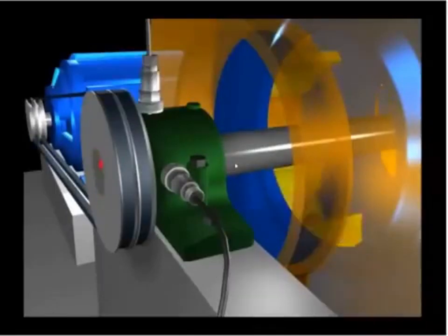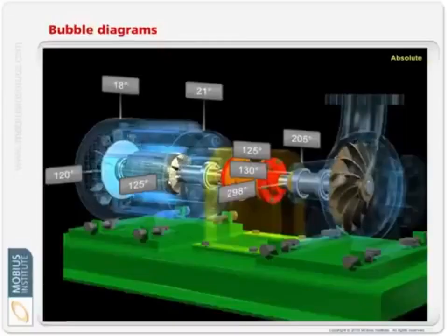Look, that's just the complicated way. You can use strobes as well. But by putting two accelerometers on the machine, in this case, one measuring vertically, one measuring horizontally, we can see how that bearing is moving. Is it moving in a circular motion, or is it more elliptical, or side to side, or up and down? We can tell. And there's an awful lot we can learn.